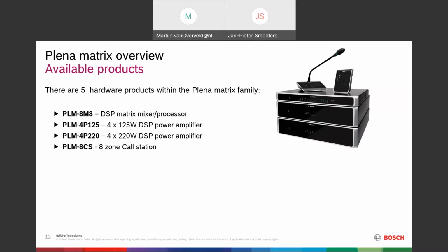So you can also control and configure these amplifiers individually, so you can use them also in standalone mode. We're going to see that later on. Then the call station, you see it here on top, for 8 zones you can address. You can easily configure the touch buttons on the call station yourself. So you can, for instance, make an all call button on this call station, selecting all zones at the same time.